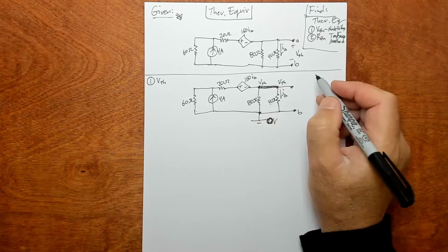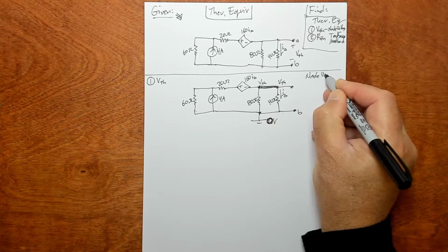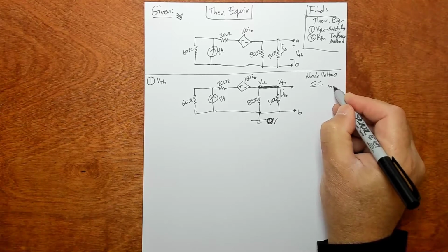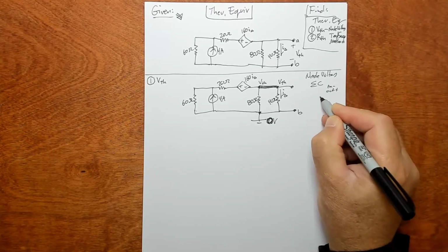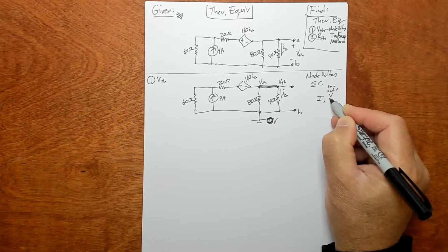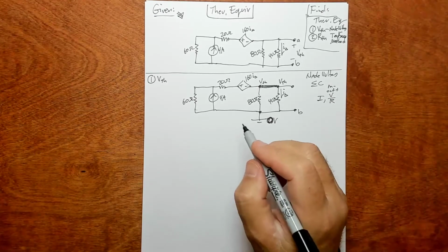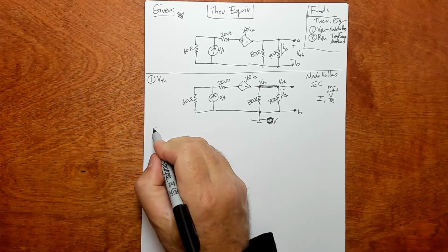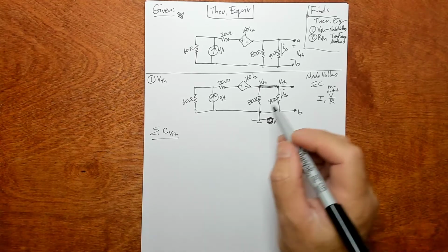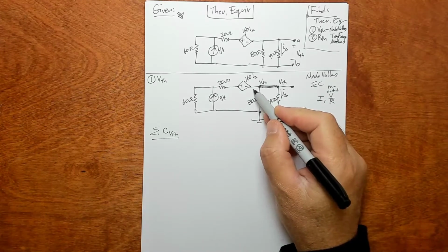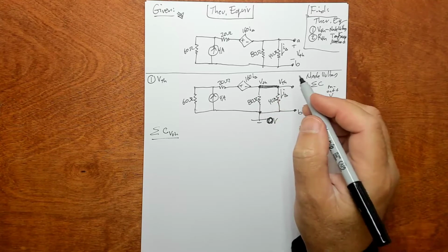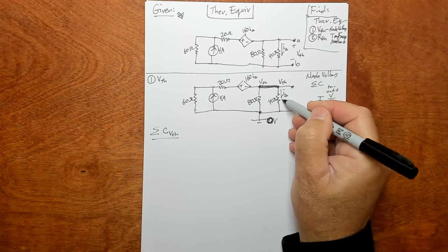And so node voltage method is the sum of the currents at a node. And we'll use in to be negative and out to be positive. And what we're summing is currents. Sometimes directly currents, and other times we'll be using V over R terms. So over here we'll write the sum of the currents at V Thevenin. So what I need to do is label all the currents on this diagram and come up with expressions for them. So I've got I delta leaving here.